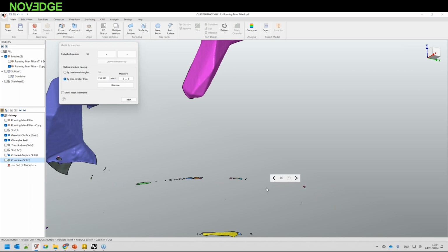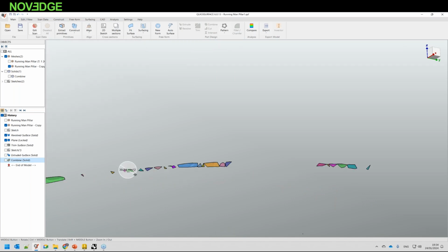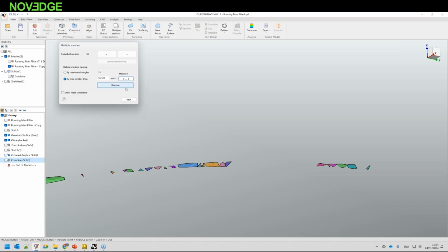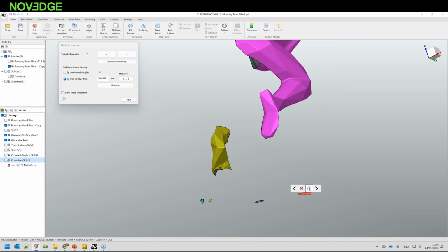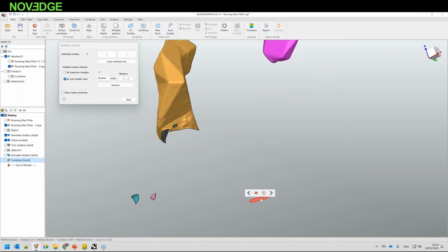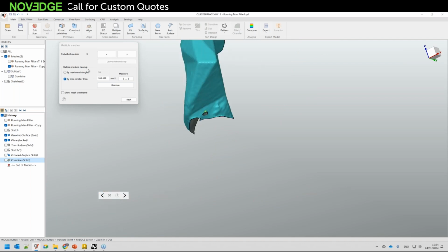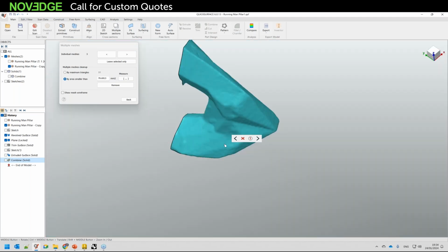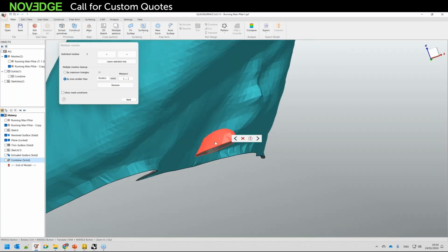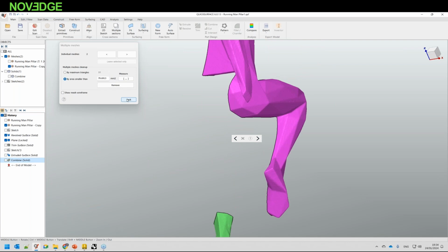But what we have as an interesting feature is that I can just measure carefully and say, okay, remove everything which is quite small, but leave the main bodies because I'm going to need them later. As you can see now, I have 3 individual meshes. I can just always track and understand what it is. In this case, for the demonstration, I'm not going to focus. I'll just stay on these main 2 shapes.